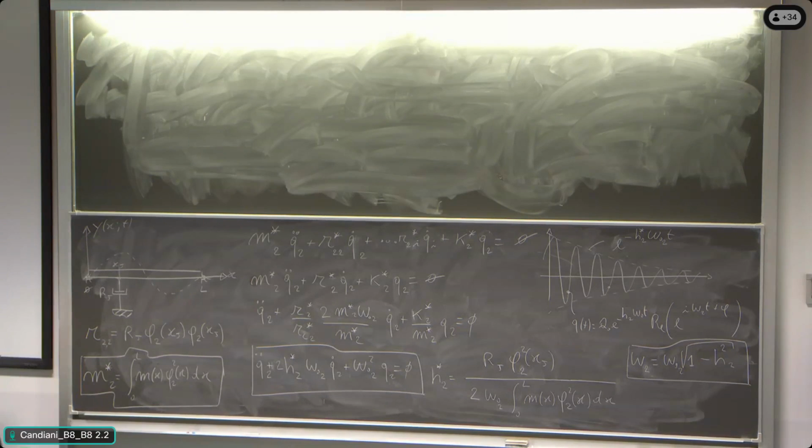And now what we want to do is to make clear that in case the coupling of the modes is not very relevant, then the damper works, adding non-dimensional damping, increasing the intrinsic non-dimensional damping of the system in the specific mode that we are looking at.